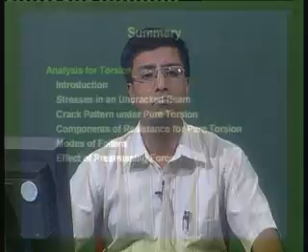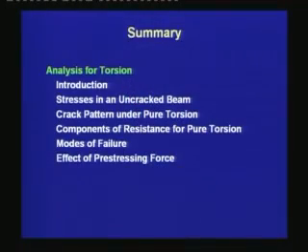Finally, we went on to understand the effect of prestressing force. What we have observed is that due to the prestressing force, the principal tensile stress gets reduced, and the angle of inclination of the cracks is smaller than 45 degrees.